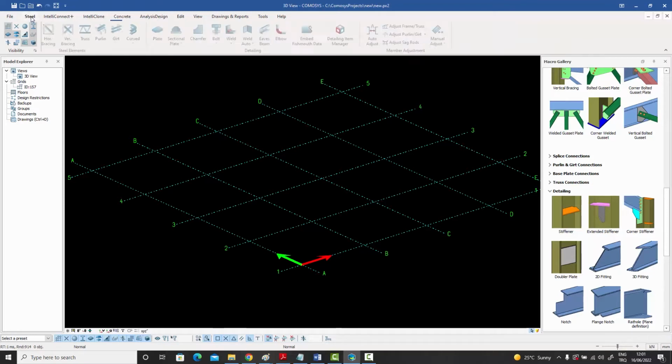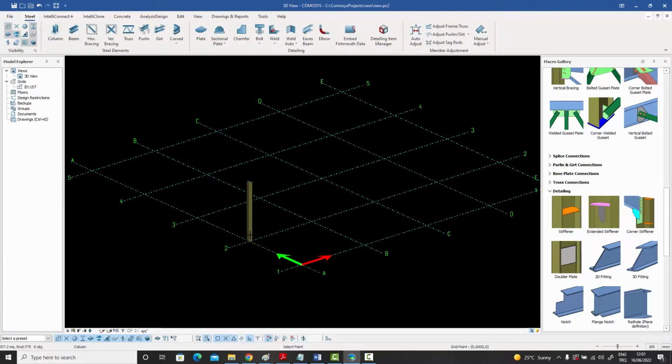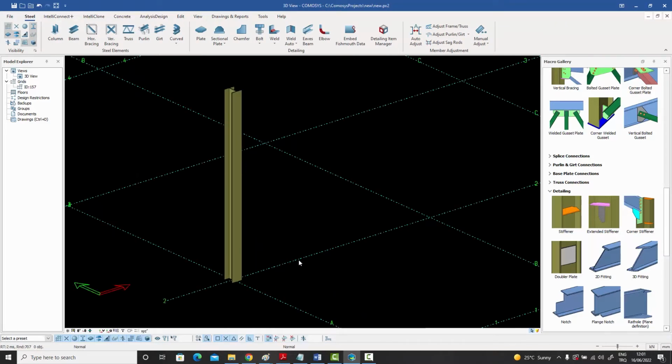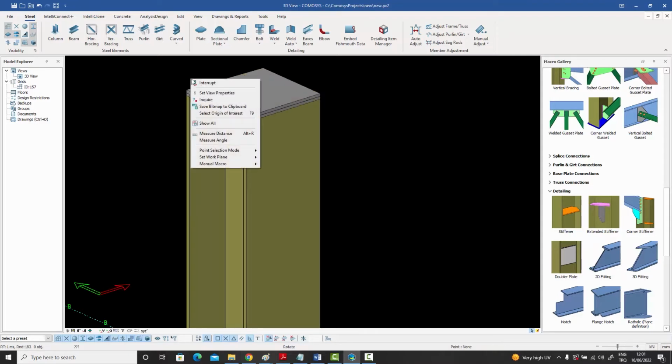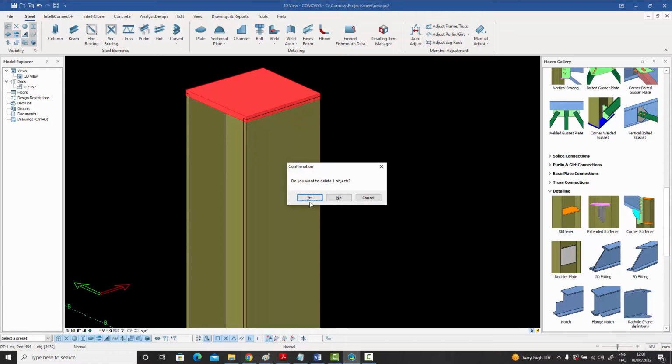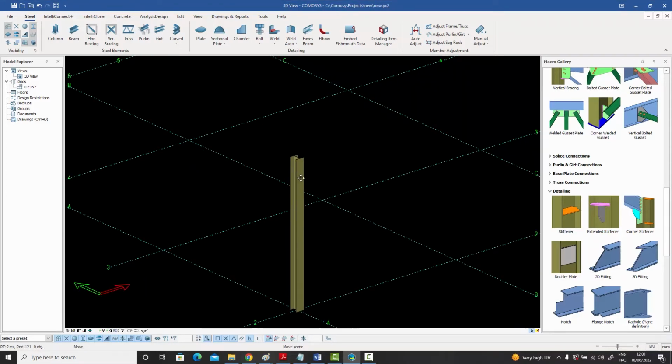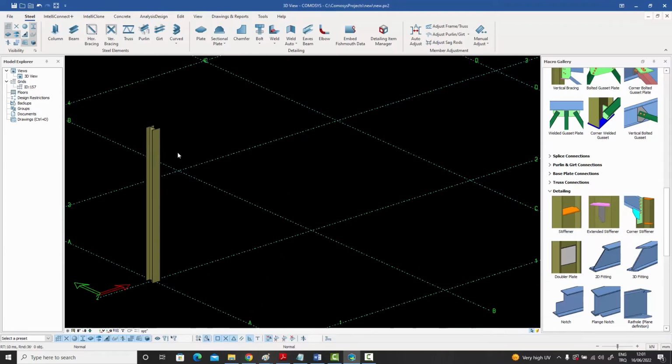So if, for example, I were to enter a column over there, the existing grids obviously supply us with many snappable points, but then the edge points of our frames also supply us with other snappable points which we can then snap onto. But the point I'm trying to make is that most commands will work with points, and sometimes you won't have those points available. So what you will need to do is create your own points if you cannot snap to something which is already there on the screen.